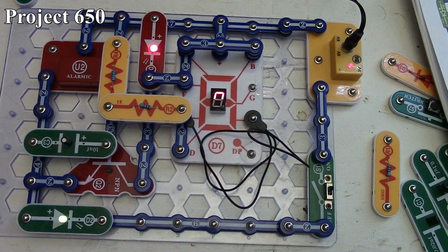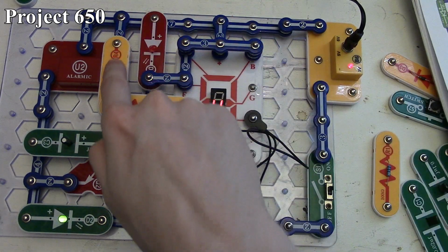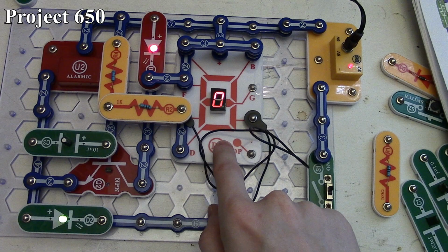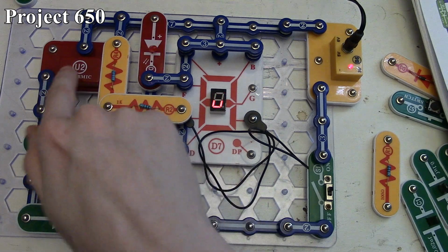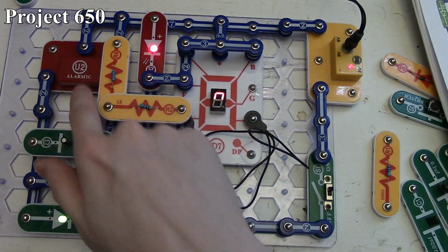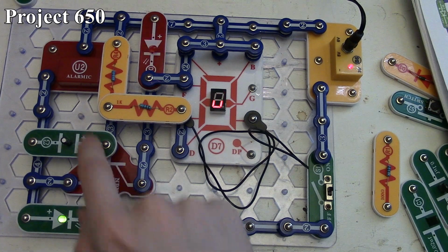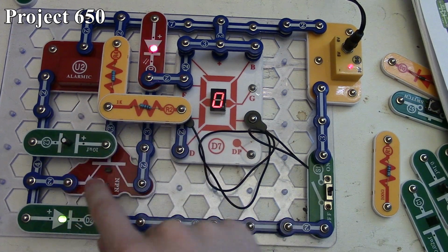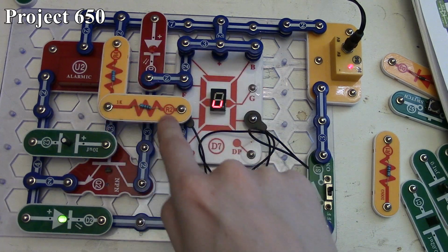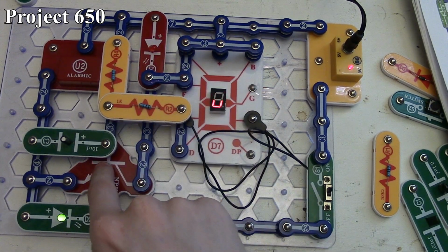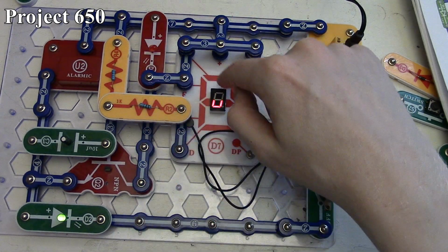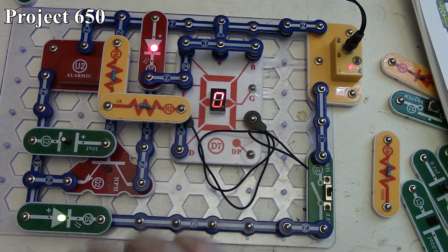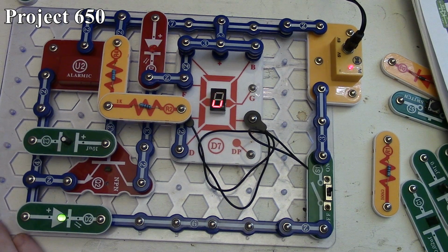And what's happening here is that normally current is going through our 2 resistors here and lighting up our bottom segments there, and because there's resistance, they don't glow brightly. But when the alarm IC provides output to the base of our NPN transistor here, that turns our NPN transistor on, and instead all the current bypasses our resistors here and goes to the base of the NPN transistor, and then of course it turns on the red LED in the top segments because that's what's connected across it, and then we see that increase in current reflected across our green LED there.